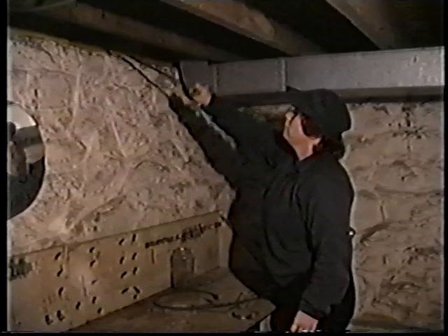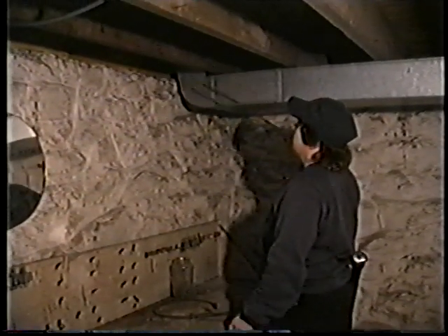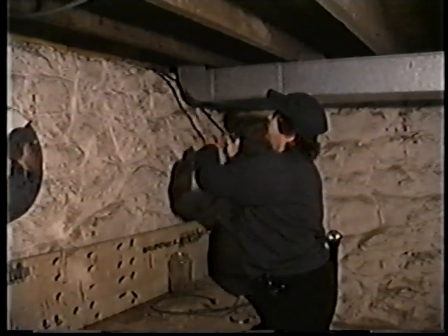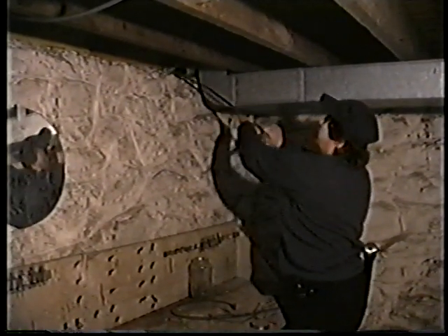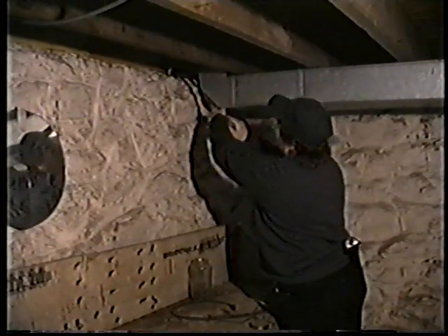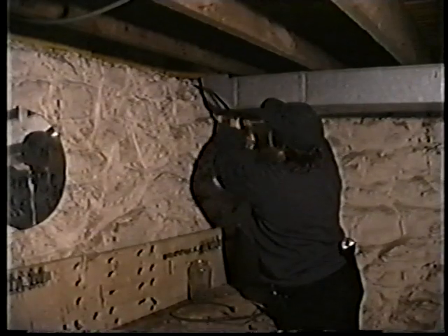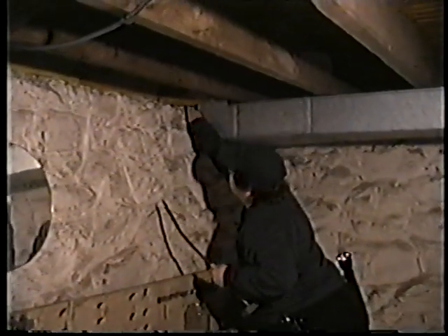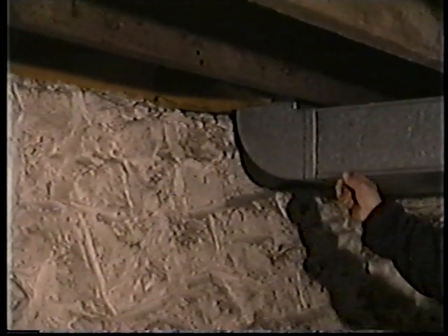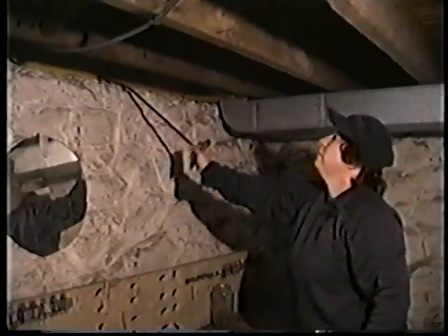Inside the house, you want to poke on the beams. In this case, there's some old foam insulation here. You can't really see what's going on underneath there. And there's some of what we would call frass here, but that actually looks like it may have been from when they cut and put this heating duct in. So your inspector's job is to actually look at the frass and find out if it's just from regular woodwork or if it was from insects. And that should be something that they could tell readily.